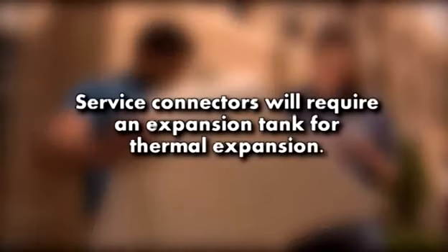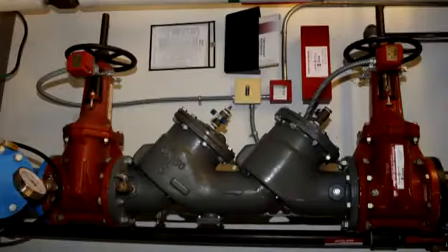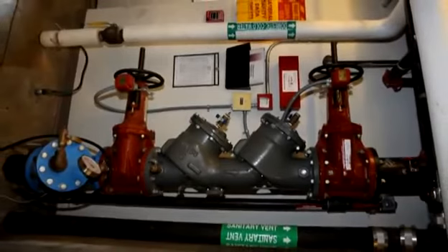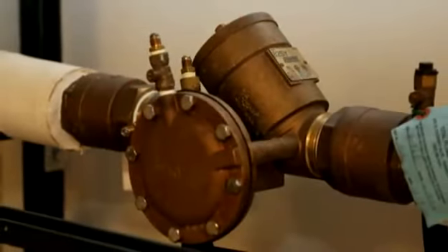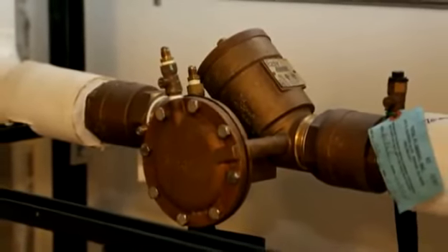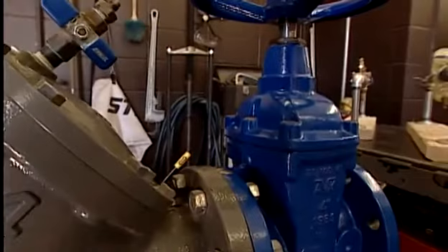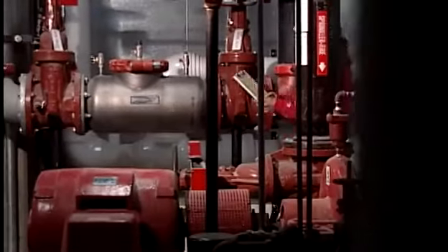Plumbers and specialists who install backflow prevention devices should be aware of several factors. Service connectors, for example, will require an expansion tank for thermal expansion. Additionally, backflow preventers produce a system pressure loss, and installers should be mindful of plumbing codes and the minimum pressure of 15 psi. Service connection assemblies do not protect the building occupants from internal cross connections.